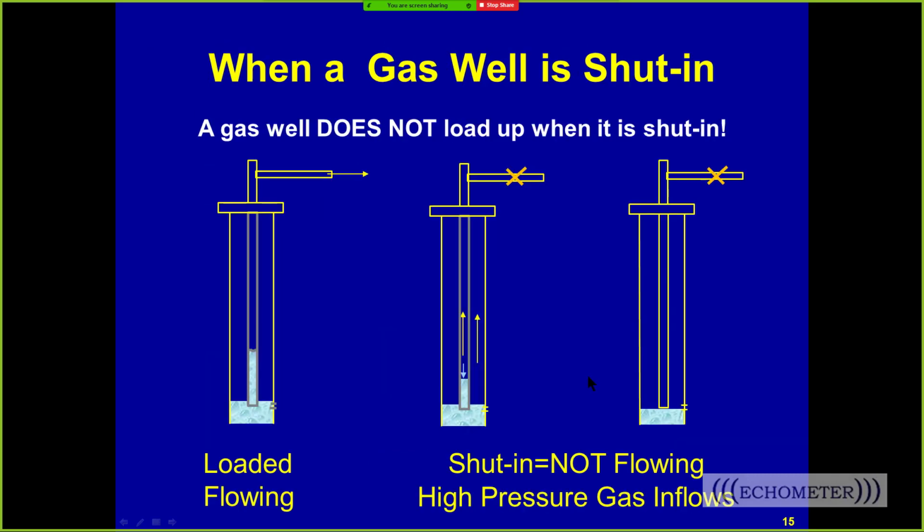Now, this is a picture about when a gas well loads up. In a gas well, the gas carries liquid in the tubing, and it loads when it's flowing. And when you shut the well in, the gas continues to flow in, the velocity is dropping, and the pressure is increasing, and it's starting to depress this liquid level right out of the tubing. And once it's shut in for enough time, in most cases I've seen 20-25 minutes, if there's not a lot of liquid, it'll push liquid out of the tubing.